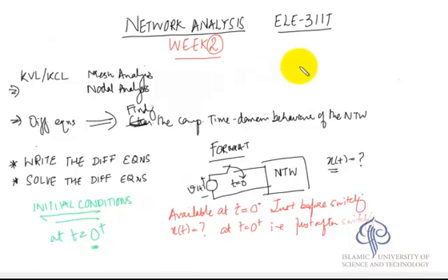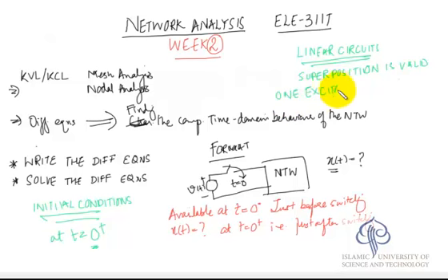The other important thing is that we should remember that we are talking about linear circuits. So the principle of superposition is valid. The advantage is that we can take one excitation at a time, see the response, and then add all the responses to all the excitations at the end.